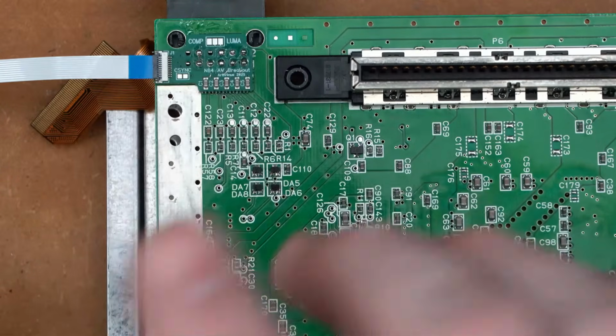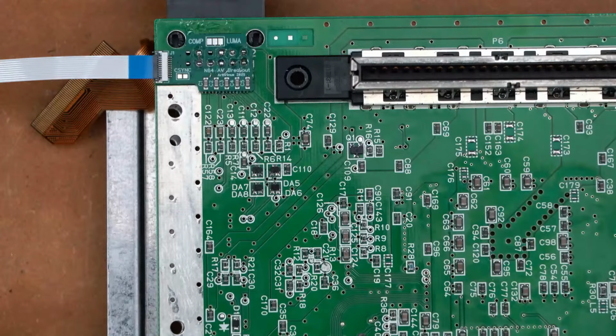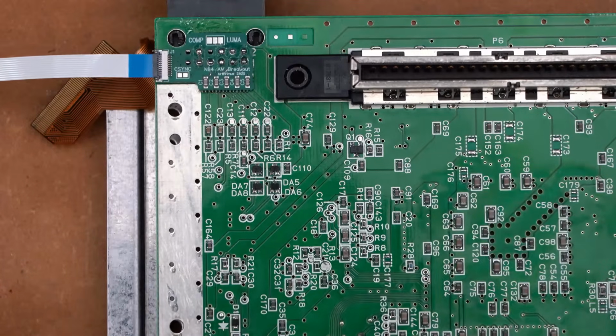The difference here is whether or not the RGB mod is the one generating and sending the C-Sync signal to the AV multi-out, or if it's the N64's own built-in DAC that's sending that C-Sync signal. It doesn't really matter because this mod doesn't do any line multiplication or anything like that. So the C-Sync is valid.